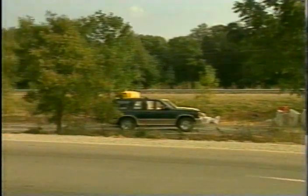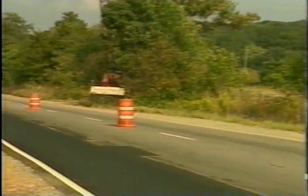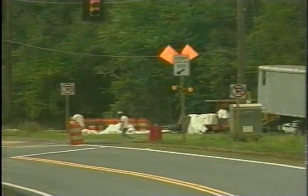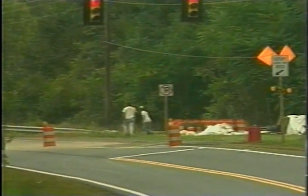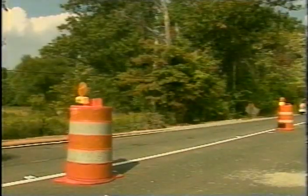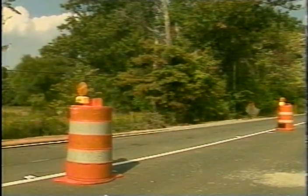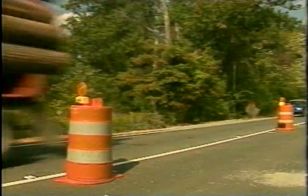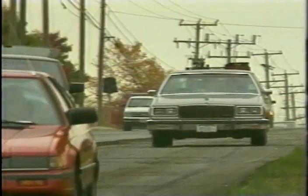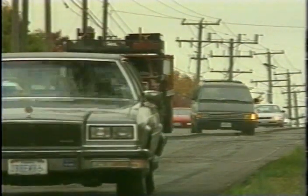Storing equipment and materials outside the buffer area, the area which an errant vehicle may need to return safely to the traveled lane. Providing workers safe access to work and storage sites within the work area. Designing detours and crossovers for a speed no less than 15 kilometers per hour below the speed limit of the approach roadway. A difference in elevation between two lanes or a lane and the shoulder is called pavement drop-off.